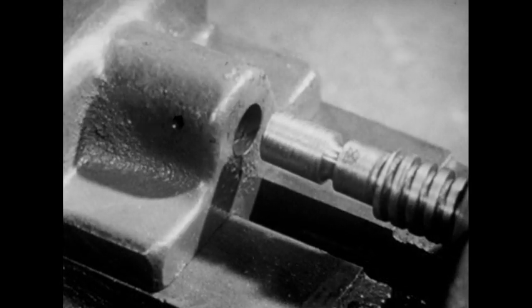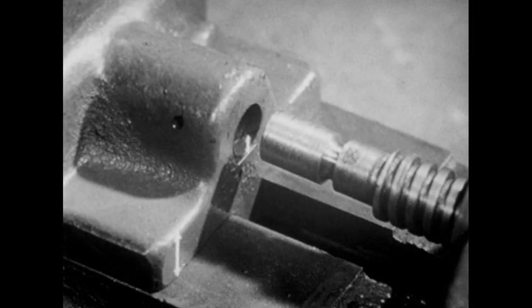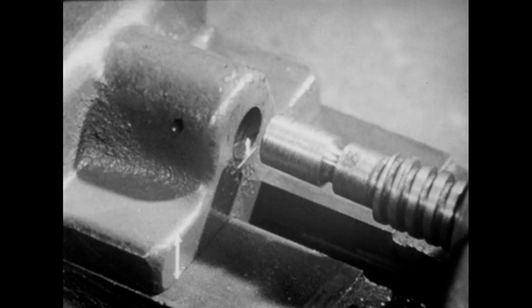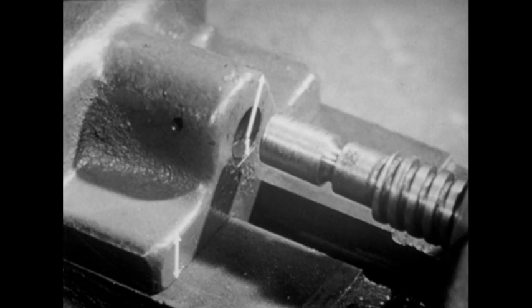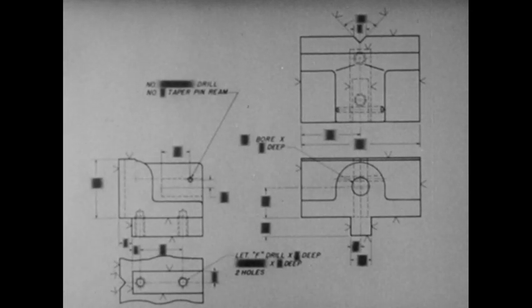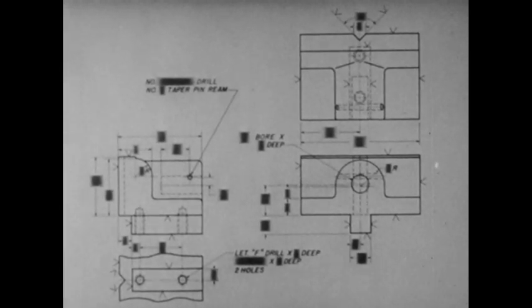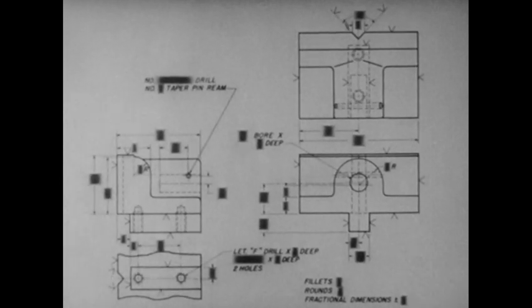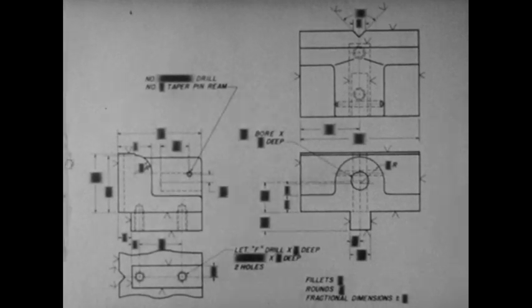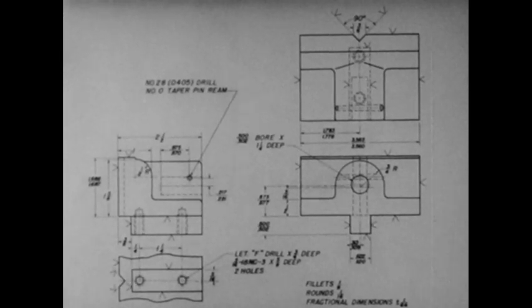He will also need the thickness of the base and the location of the center for the semi-cylinder. Give the dimension of the semi-cylinder as a radius. This is acceptable to the pattern maker and follows the usual practice. Follow the usual rules for placing these dimensions on the drawing. Give the necessary notes for fillets and rounds, and you have finished the dimensioning of the movable jaw. Instead of these symbols, which have been used here to stress the principles involved, you will, of course, use actual dimension values on your drawing.